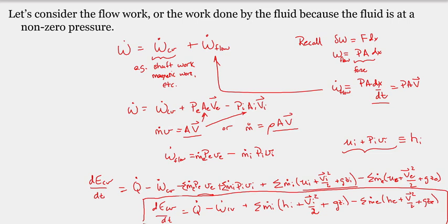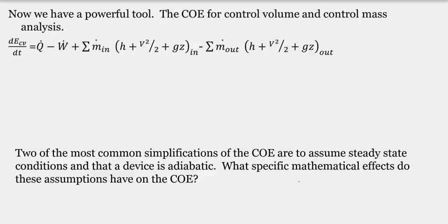It's the most important form of the conservation of energy expression. So if we have control volumes, we work with enthalpies. If we have control masses, we work with internal energy. Okay, so you're going to see this equation again and again in our expressions here. Now here it is repeated in a much prettier form: conservation of energy for a control volume.